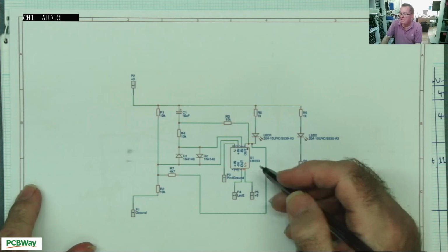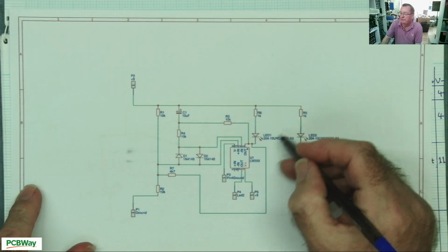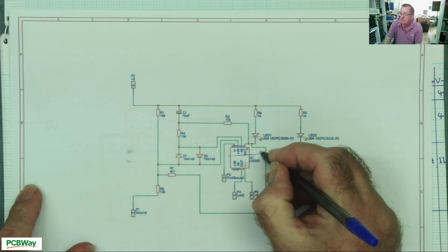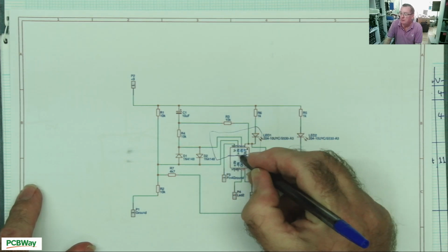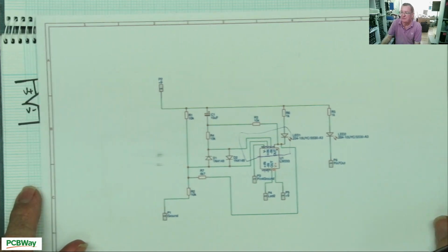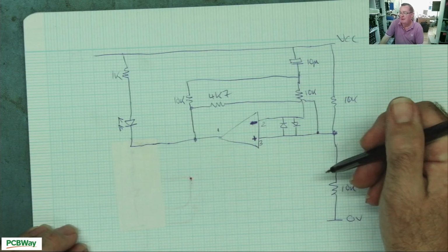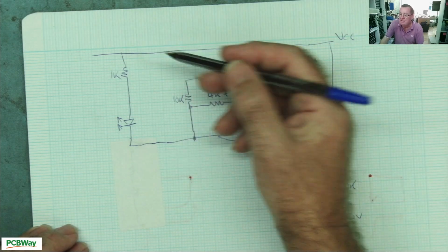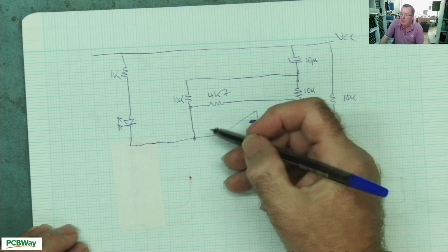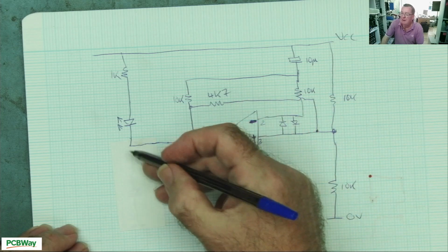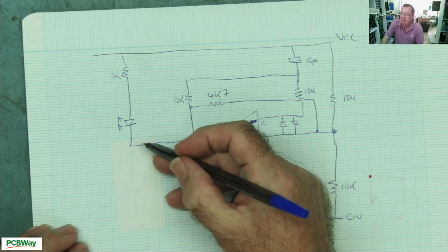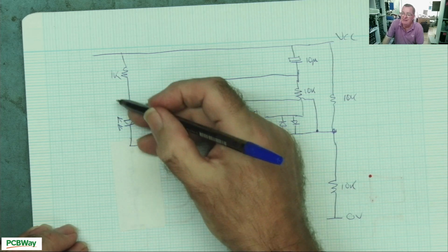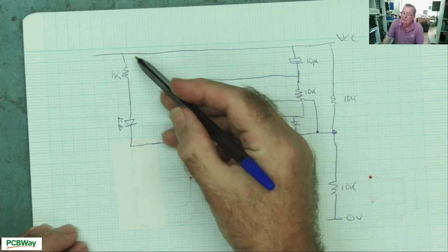And I based it on here. I took out all the stuff for the second comparator, so just looked at this one effectively. Okay, and what I came up with is this. So in actual fact, the circuit is the same as the op amp tester. The only difference being that the op amp tester drives the LED. So it puts voltage on the LED. The other one's connected to ground. It's connected down here. And this version actually sinks power.